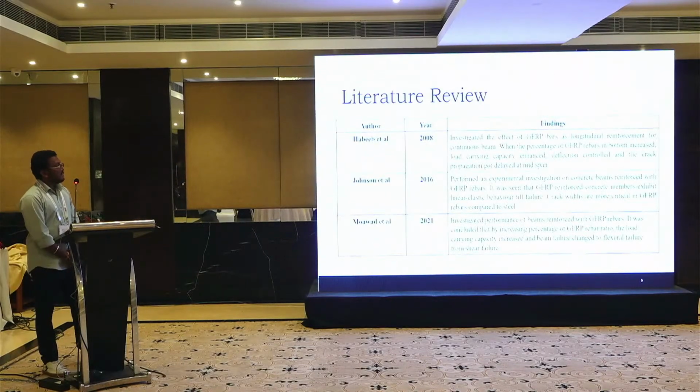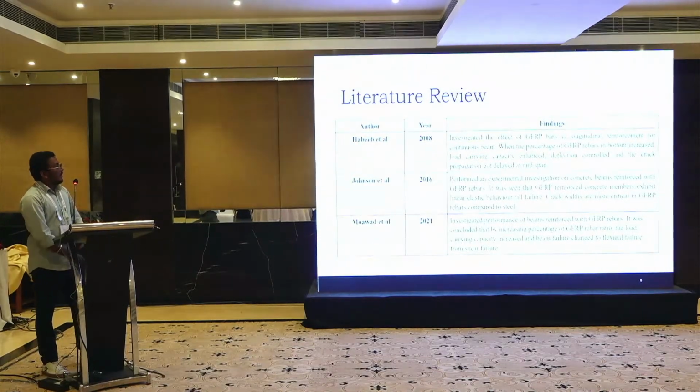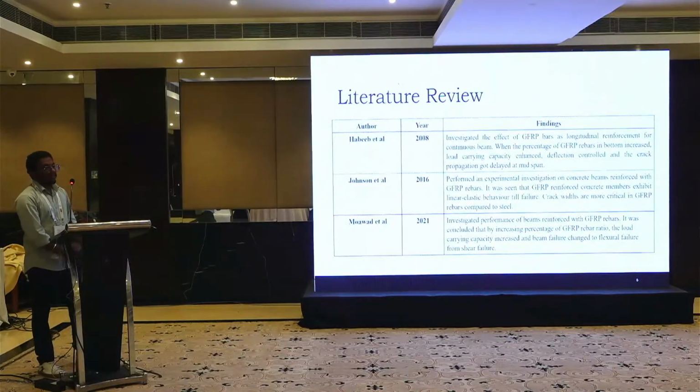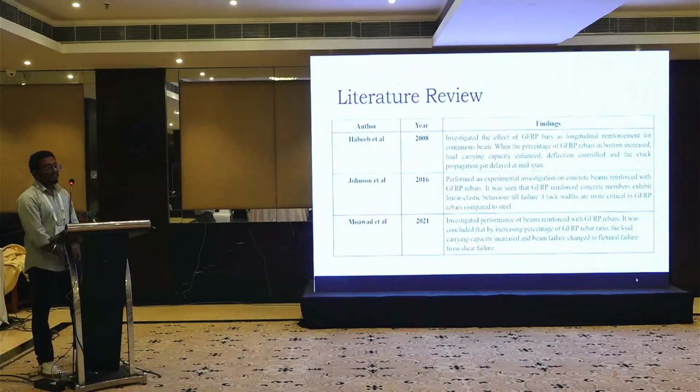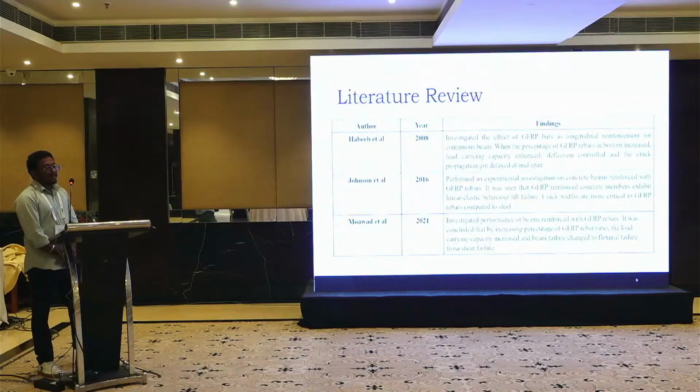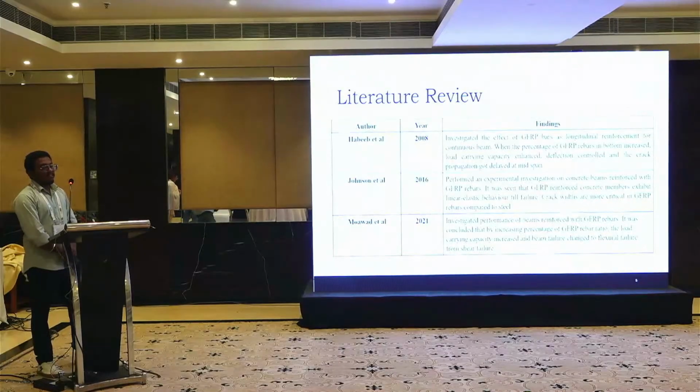These are the literature reviews we went through, like Habib et al. in 2008, and many others, which mainly told that replacing steel reinforcement with GFRP bars exhibits more and wider cracks when compared to steel reinforcement.